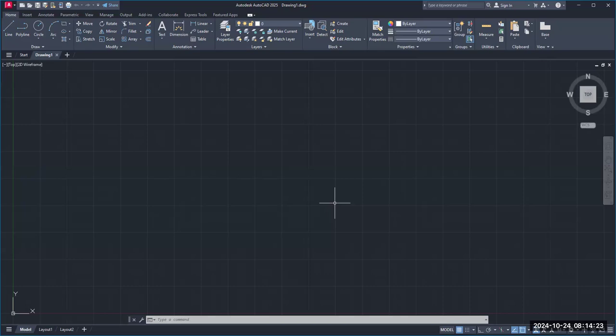All right, so the first thing we're going to do is look at our drawing and at the overall size of this block. We have determined from the ordinate dimensions given here that the length of this block is 3.625, rounded off to 3.63, and the height of this block is 3 inches.